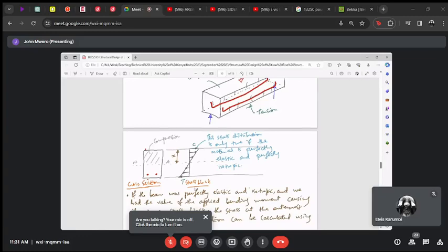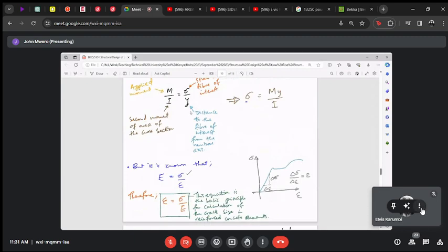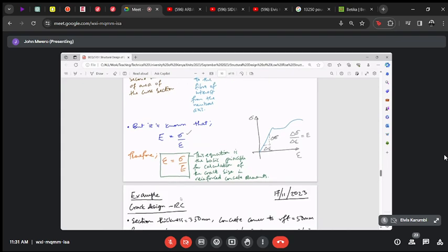Look like. And we saw that that stress block can be calculated using this equation here, and therefore we can actually calculate the stress. Now, if we know the stress and we know the Young's modulus of elasticity of a material, we can actually go ahead and calculate the strain. Now, this is the foundation of how cracking is calculated, because we're saying the element is bending. Can we calculate the stress at the surface that is most stressed in tension?